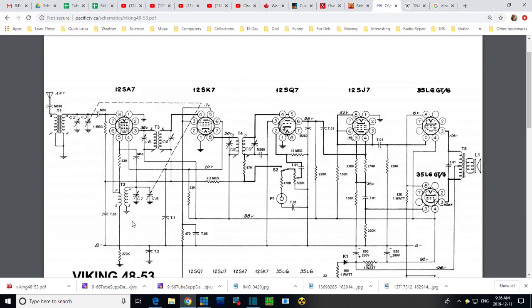So again, when you turn the knob in this radio, you're tuning two things. One is you're changing the frequency of the local oscillator, like that in all these radios. And you're also moving the front end tuning along. And alignment is getting these two things to track together, so they're at the right spot to work together. That's part of what's going on when you align a radio.